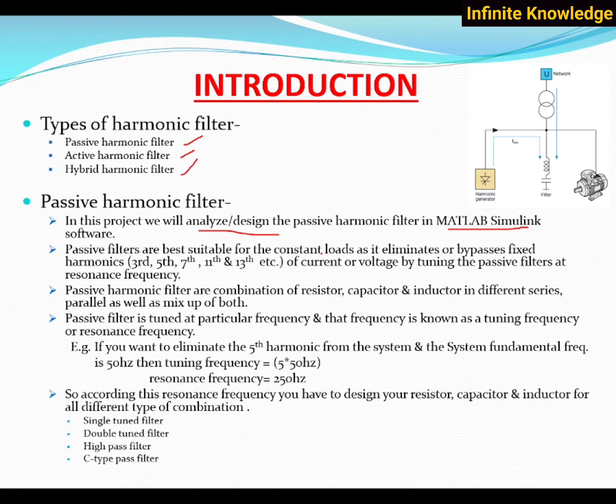You can connect with any vendor that is doing harmonic studies. They come to your industry, put the harmonic analyzer into your system, and check for 1 to 2 days what your level of harmonics is and which harmonic levels are continuously changing in your system and spoiling your system.